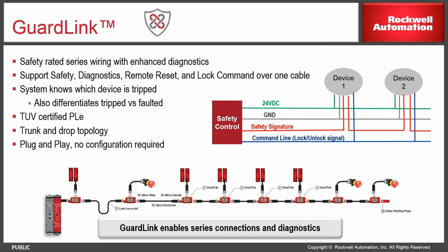So imagine how much easier it will be to troubleshoot the safety system when you can simply put a message on the HMI saying that a safety system is tripped. So say, close door number 4, or select or clear the e-stop number 3 and reset the safety system. So this saves a lot of time. You are able to access, pinpoint and identify the fault in seconds.